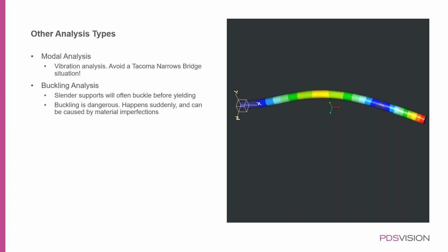Not only can we hit that tensile yield stress, but additionally, we have to keep in mind that this thing can buckle as well. It's a separate thing that we have to test. Buckling can happen after a failure due to stresses, or it can happen before. It's just something you need to simulate to find out.